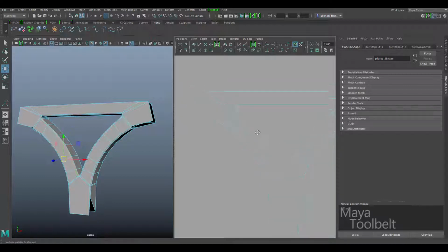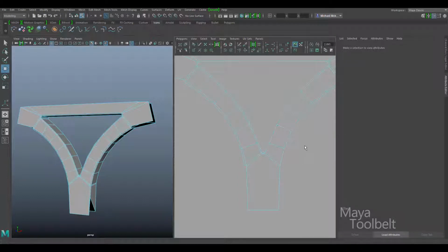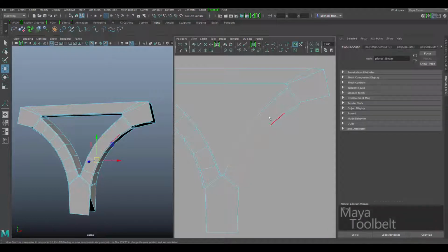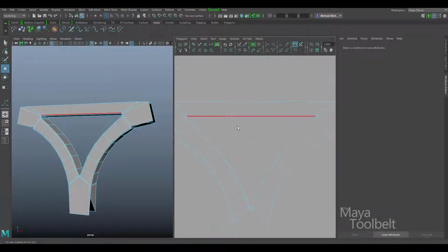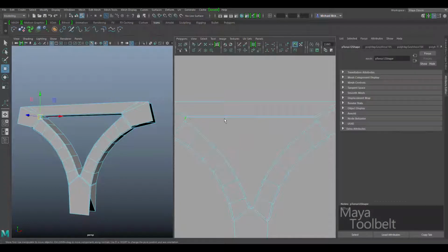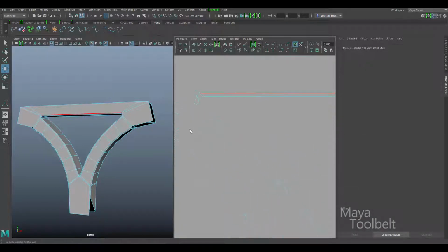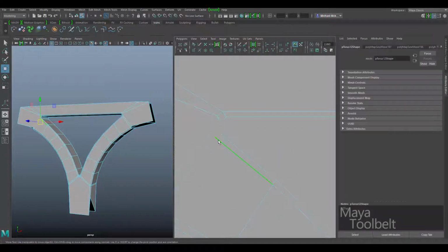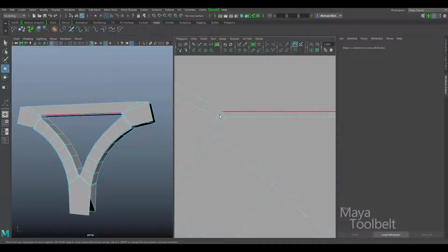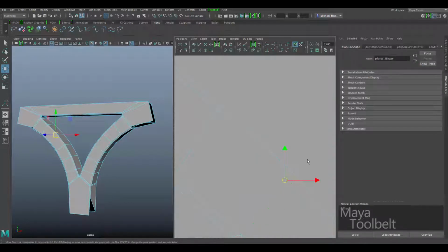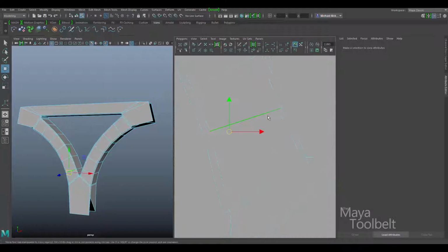So what we want to have happen, I can select these edges, and what I want to see is when I move and sew, only those little thin beveled corners move over here, like that. That's what I want. Do the same over here. Move and sew. Move and sew that one. And these little ones in here. And then I can move and sew, or just sew, either way, just to connect all these little pieces together. So we don't have these gaps like this. You can say move and sew, but they won't move, they'll just sew together since they're attached to this piece.